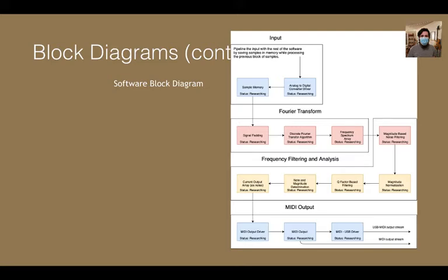And from there, we ended up, rather than using Q factor-based filtering, we decided to go with a harmonic product spectrum algorithm, which decomposes the harmonics and multiplies them into the fundamental bins, which will exaggerate the magnitudes of the fundamental notes being played. And this allows us to choose the fundamental frequencies and distinguish them from the harmonics and any sort of noise.